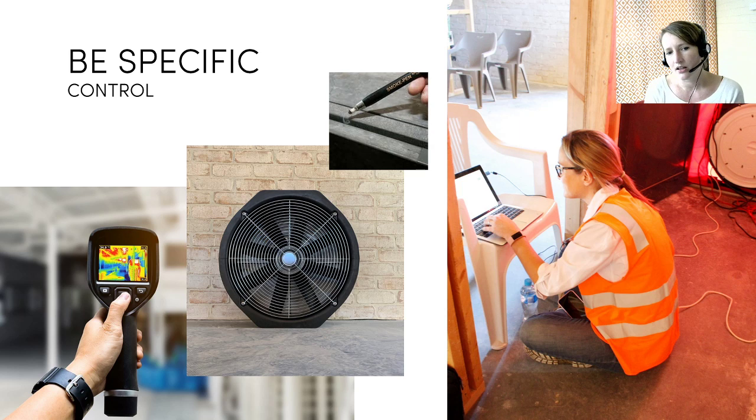Having a go around with a thermal camera at the end of the installation of insulation to be sure that nothing has been removed. Maybe after electricals and plumbing, to be sure that nothing has been moved and torn away after some work. We can also use a smoke pen and other techniques to find out where the leaks could be, if there are leaks that you want to sort out. So here is a photo of Jess again doing the airtight test in the 10 star.